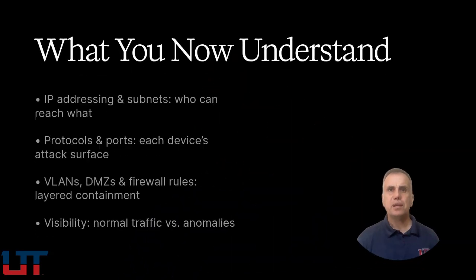You came into this course with experience operating SCADA systems and industrial control equipment. You're leaving with a specific understanding of how the networks underneath those systems work, and why the way they're designed, configured, and maintained determines how defensible they are. You understand how IP addresses and subnets define who can reach what. You understand how protocols and ports define what attack surface each device presents. You understand how VLANs, DMZs, and firewall rules create the layered architecture that contains breaches and limits blast radius.